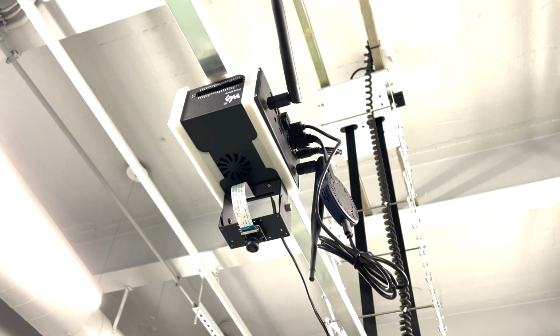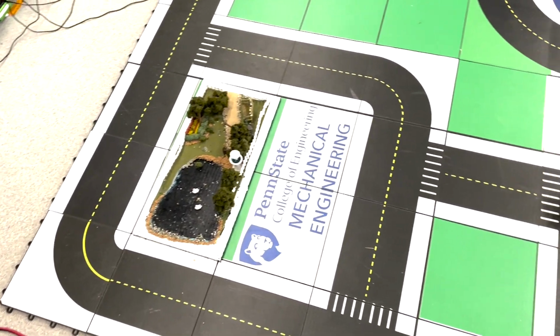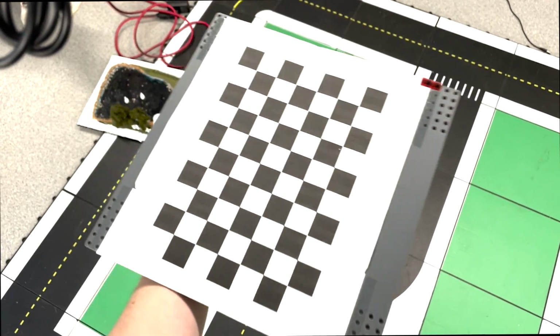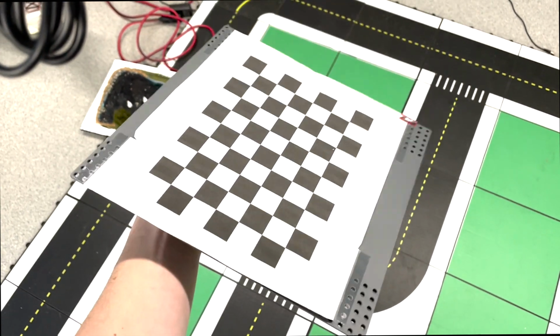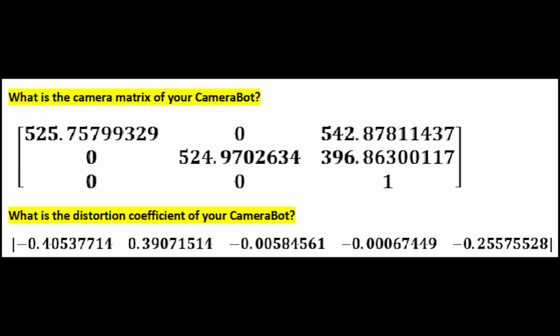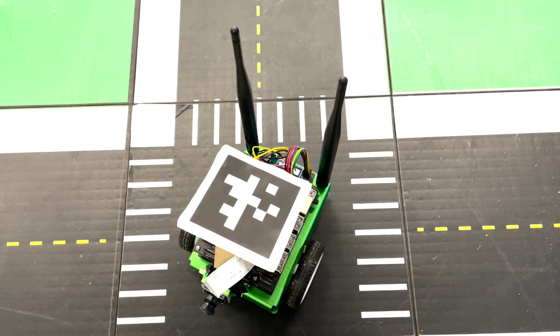In the third lab, we utilized communication between the JetBot and CameraBot. After connecting to the CameraBot, we were able to take pictures of the road map. Once we successfully gained access to the camera, we were able to calibrate the camera using a checkerboard at various orientations. Upon calibration, we determined the CameraBot's camera matrix and distortion coefficient, which we were able to implement into our code. On top of the JetBot is an identifier called an April tag.